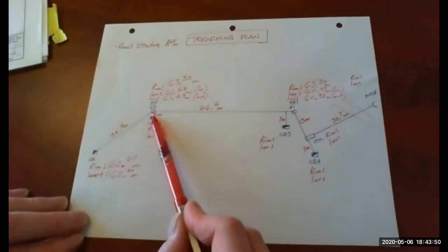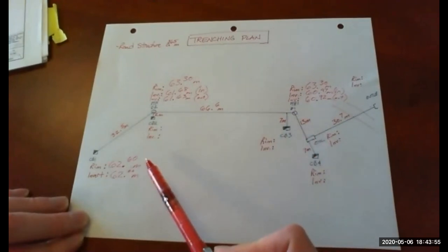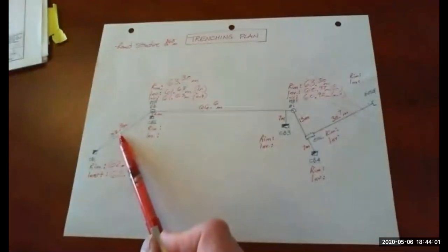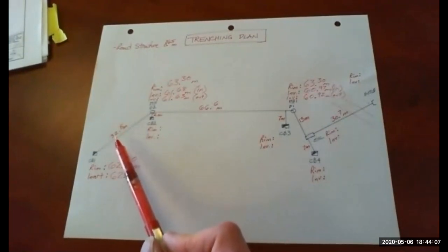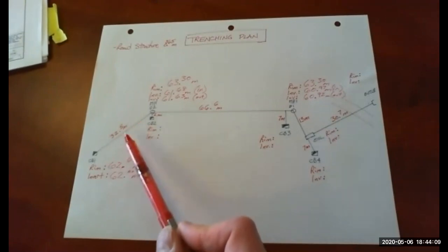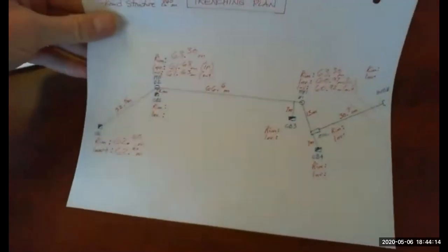For the catch basin leads, you had to scale those. You had to measure those off of your drawing. So I scaled for CB1 lead, I scaled 32.5. If you were slightly different than that, I didn't mark you wrong. As long as you were in the ballpark within a meter or 2, it was fine. Okay, so we'll come back to that.